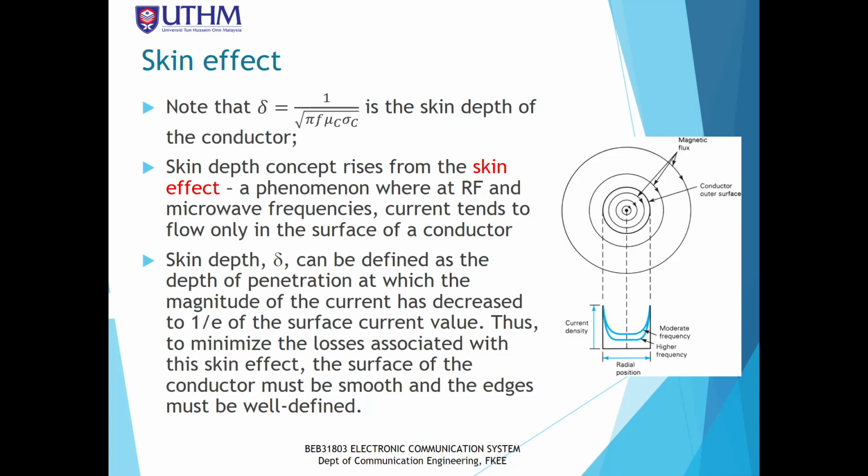Normally we expect the wave to travel at the core of the conductor, but at high frequency it travels at the surface. That's why we call it the skin effect, as if the wave travels at the skin of the conductor. Previously we asked: briefly explain the skin effect. It is a phenomenon at high frequency.